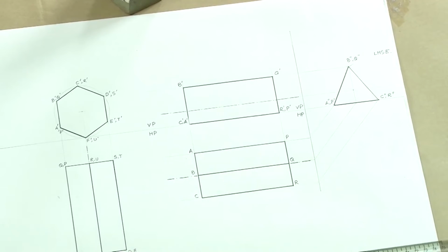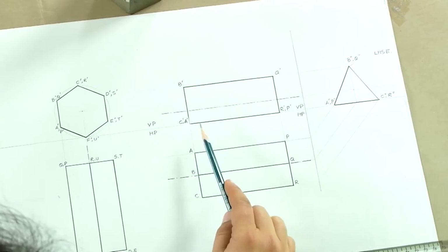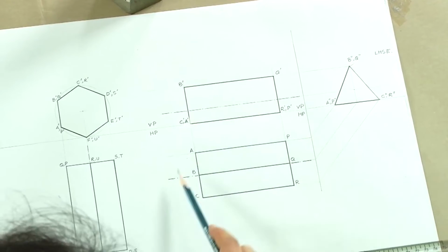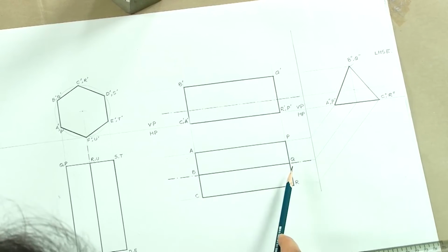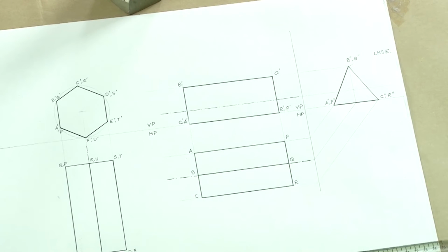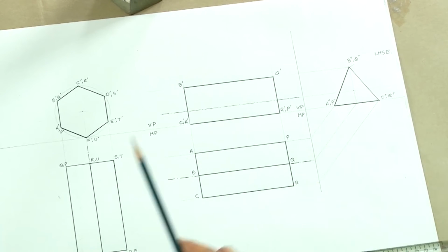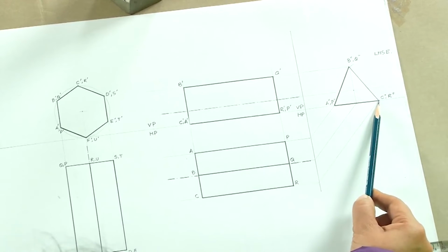And now you see that since the axis is parallel to both HP and VP, we are able to see the axis fully in both these reference planes, and it is in its true dimension. While the triangular face, we were able to see the true dimension only in the side elevation.